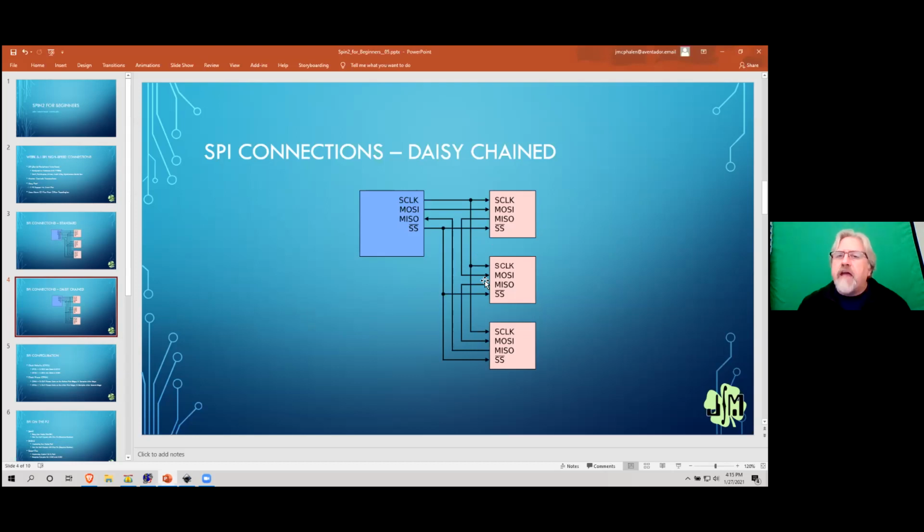Now, they're not live real-time inputs, but this is an industrial type controller, and I have background code that reads the inputs every millisecond, which is plenty fast for what we're doing with this device. But what that allowed me to do, using SPI devices, in this case the 74HC165 input shift registers, was create 16 inputs out of 3 Propeller pins.